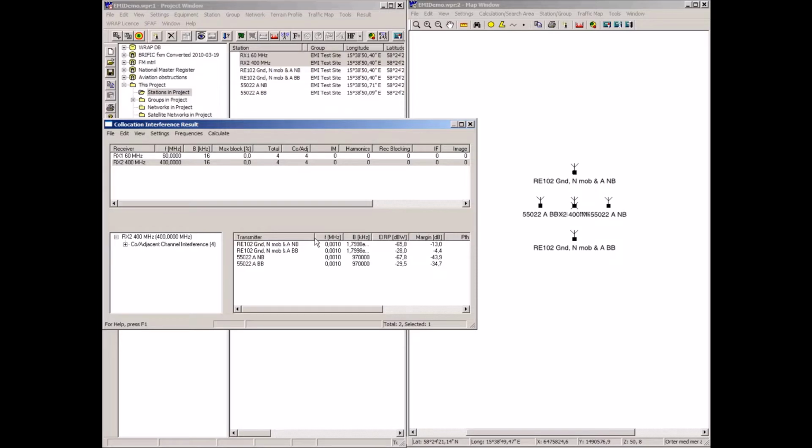The civilian standards are simply not sufficient. If there are these computers in this staff headquarters, they will produce a lot of interference if they are installed just without any protective measures. If they are installed in shielded enclosures and very careful shielding and decoupling of connecting cables, then it may be okay.